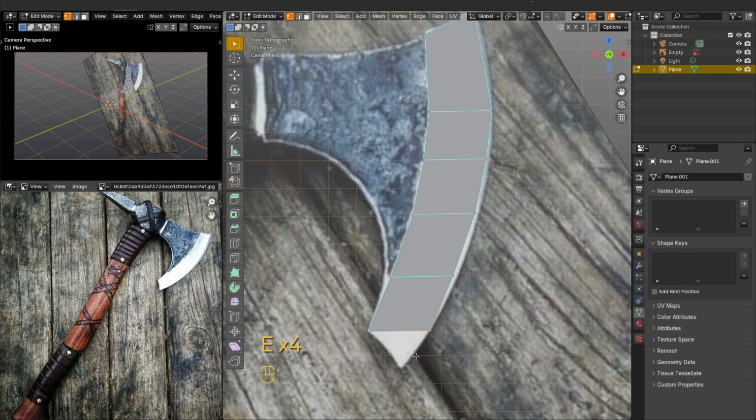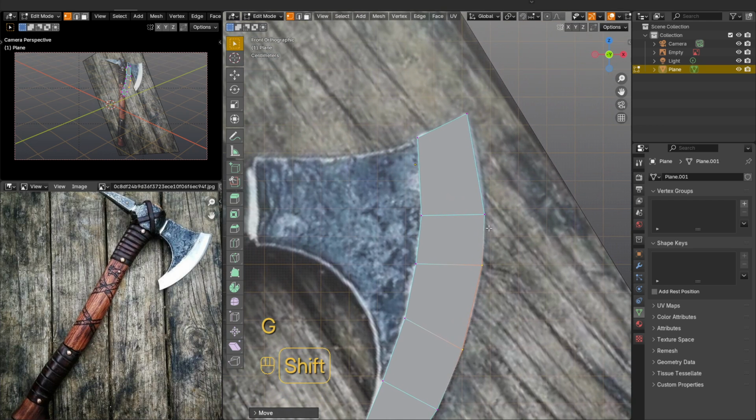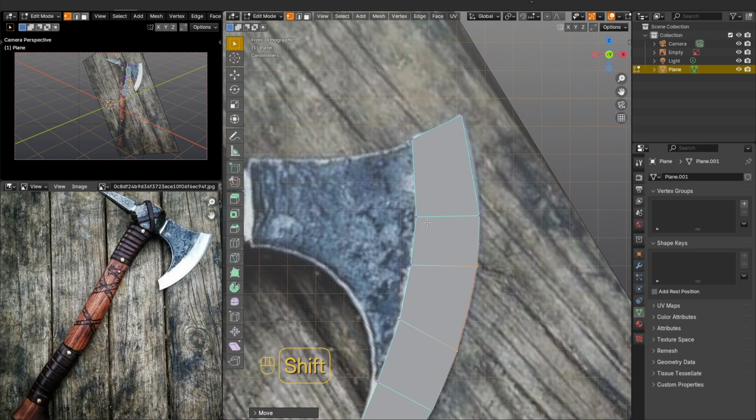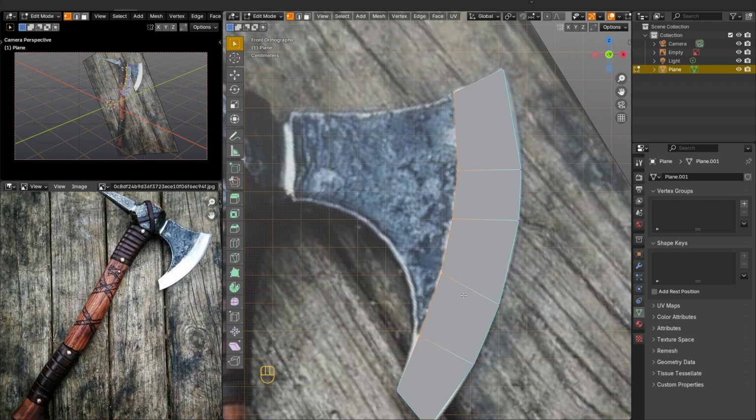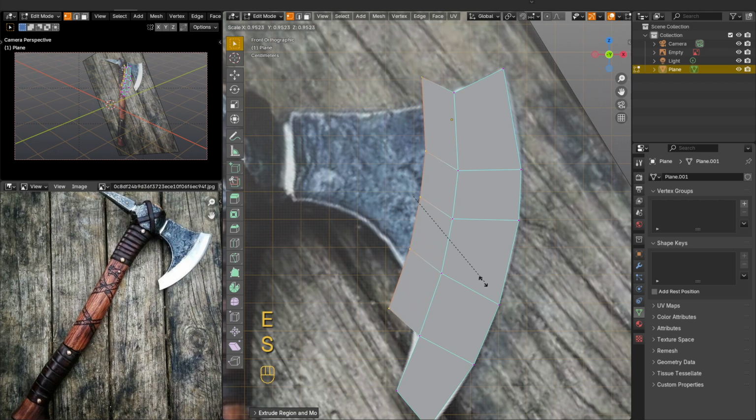At the same time, remember the main rule: the fewer vertices, the easier it is to manage the geometry of the model. Now select 4 of the 5 vertices and extrude them along the X-axis, but do not cancel the selection, and immediately press the S button and reduce their size a little so that they match the reference. Do not forget to correct the previous vertices so that everything looks nice. I recommend keeping everything in order from the start.